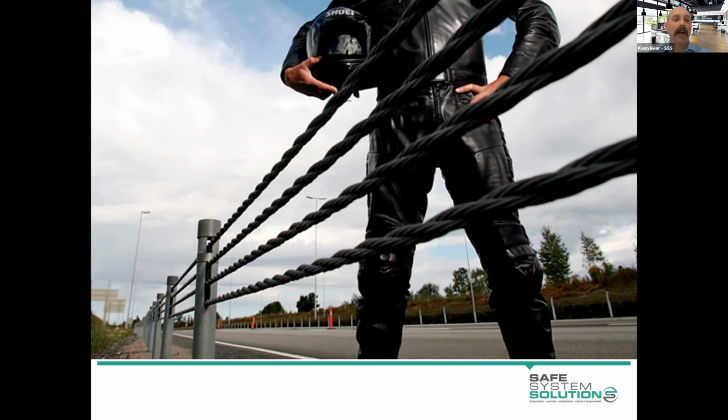So for me, if it's a popular motorcycle route, my choice of barrier system isn't going to be a wire rope system anyway. The reason is it probably has some curves, so I can't use it, and I don't have the ability to add an underrun protection device that is really good and tested. So I'm going to use a flexible W-beam system and its proprietary underrun protection. That's just going to be the choice of barrier system. But for these long stretches, like a Hume Freeway upgrade or whatever it is, I'm still going to use wire rope safety barrier because the motorcycle risk is so minuscule.